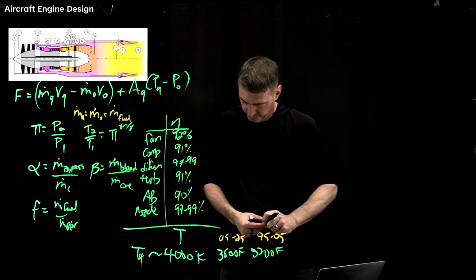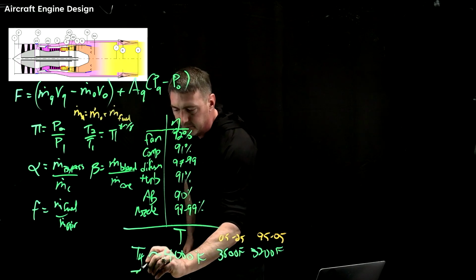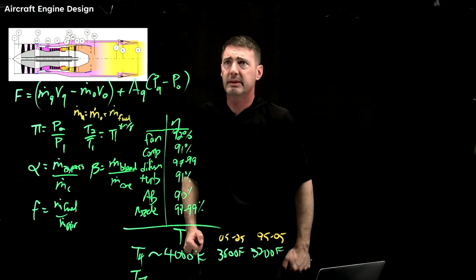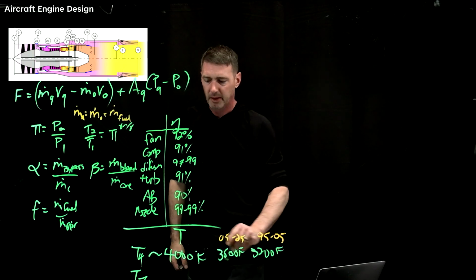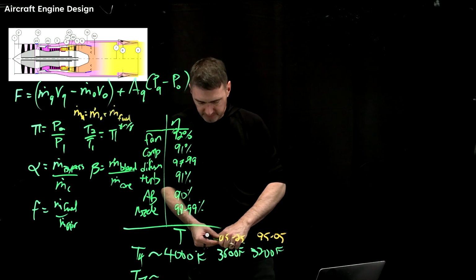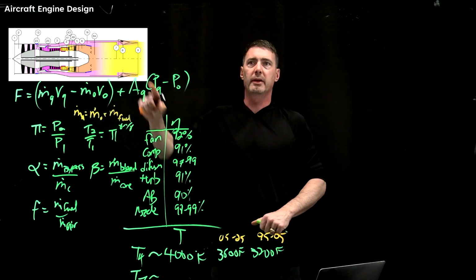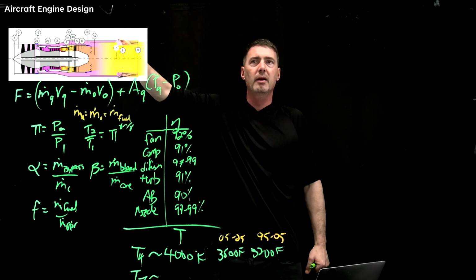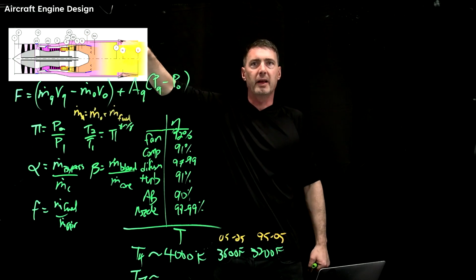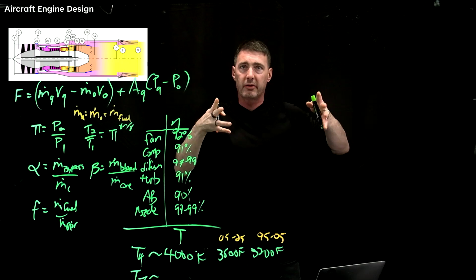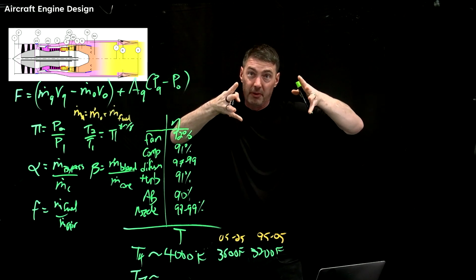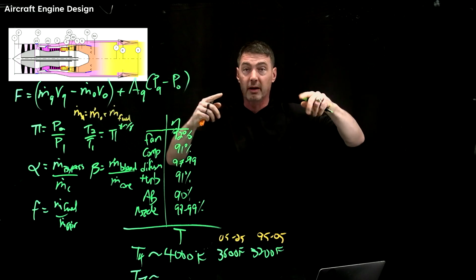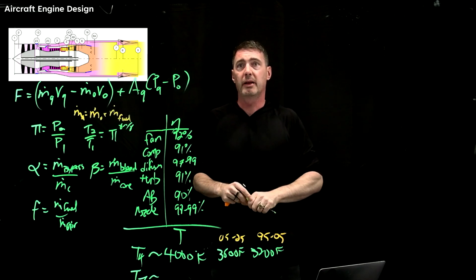All right, and then T7. Look at the diagram. That's sort of afterburner exit temperature. Afterburners usually can handle a little bit more. Some of it is that you have some of the air from the bleed providing a bit of a barrier. If you take a look at afterburners, there are also these ducts that try to keep the flamey part on the inside, and then you run a little bit of cool air. It does mix a little bit. You're not going to get away with that.